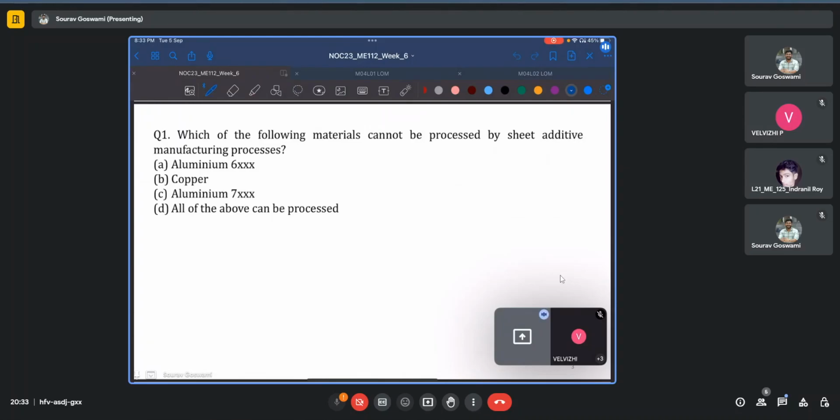So usually in any other additive manufacturing process, such as in DED, because of the very high reflectivity of these aluminum and copper materials, as well as the very high thermal conductivity, what happens is that the materials are not properly melted because a large part of the energy which is incident actually gets reflected back. People have done it, but it still cannot be performed reliably. And the additive manufacturing of aluminum and copper remains still an open challenge.